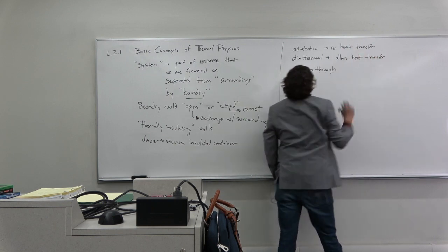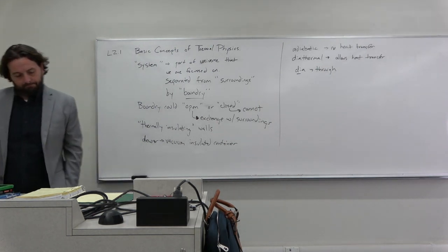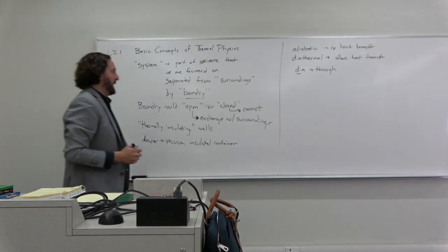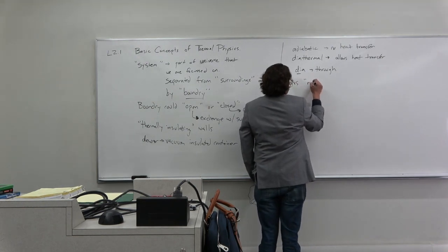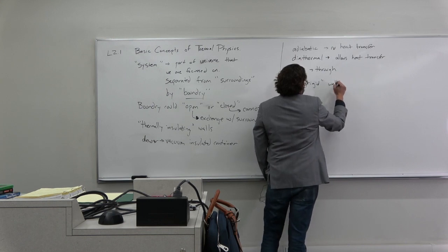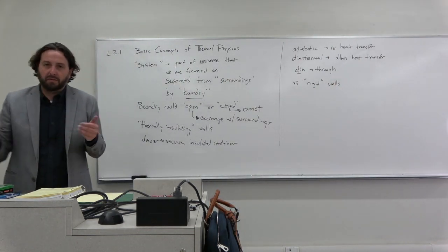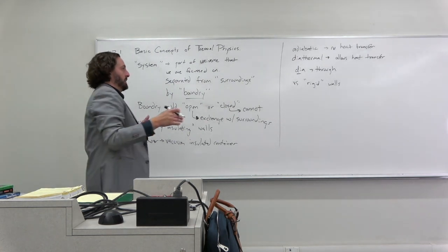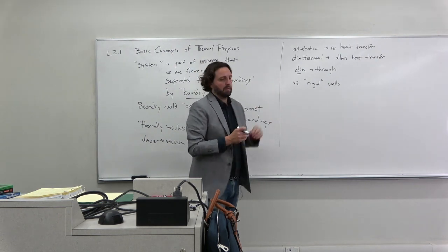In this context, we really mean no heat transfer when we say an adiabatic wall. Now you can compare that versus what we'll often call rigid walls, right? So you could imagine having a styrofoam membrane that's thin enough that it flexes, right, and allows some non-rigidity, some mechanical energy to pass through, but no heat transfer.